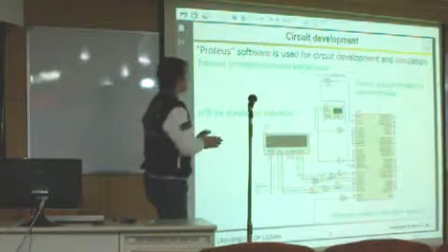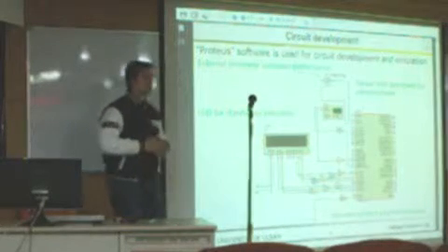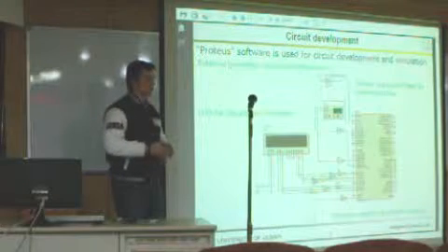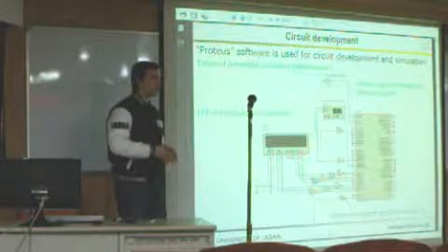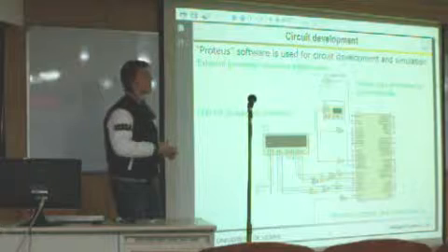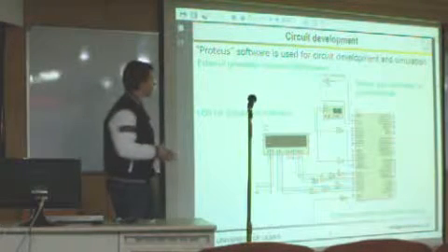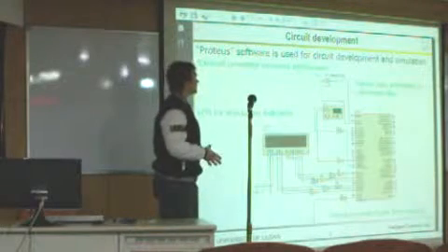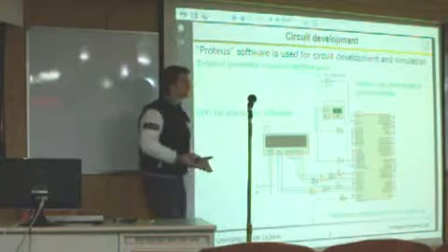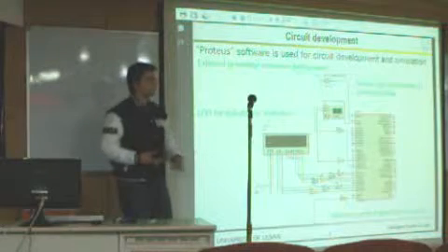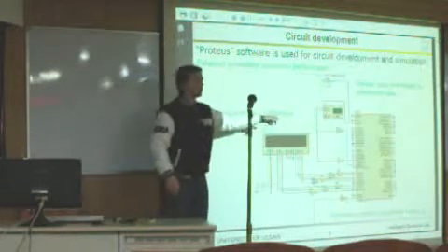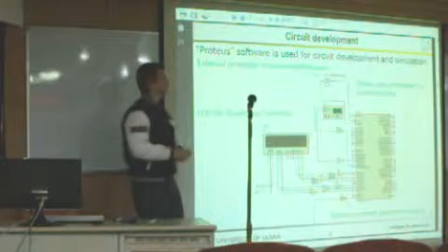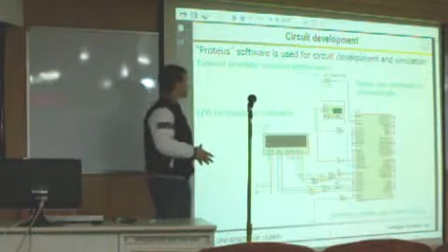I'm developing circuits in Proteus software. This software allows me to simulate this circuit without creating a real one, before creating a real one, in order to prevent burning of real hardware. In my circuit, I'm using an external generator which increases performance to 16 million instructions per second, because the built-in crystal works at 1 megahertz frequency, but I'm using 16 megahertz frequency.